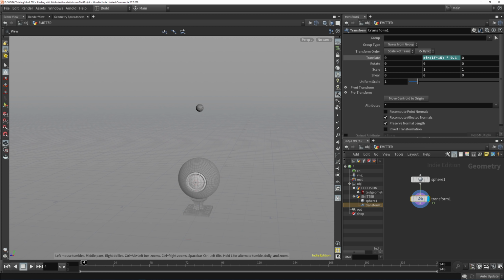See what that brings us if I hit play. Okay, that's very fast. So I guess we should go a lot slower than that and reduce that by maybe, let's try 5. See what we get now. Okay, and now let's view it in real time. If you click that clock on the bottom, it forces it to limit to FPS. So this is actually now a bit slow maybe, so let's go back up to 10. See what we get now. All right, that's pretty cool.